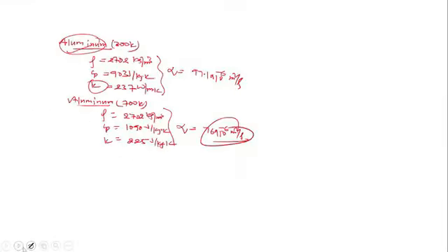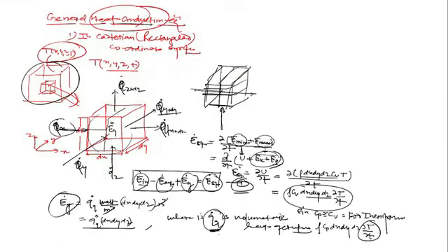So what I can do here, if one dimensional heat conduction is there, then out of this geometry, whatever I had taken here, in this case, this is my system, and if in this system temperature is only a function of x, then we should assume the differential element only in, tell me, if temperature is only going to vary with x direction, then we should assume the differential element only in x. In y and z we should take as a whole.